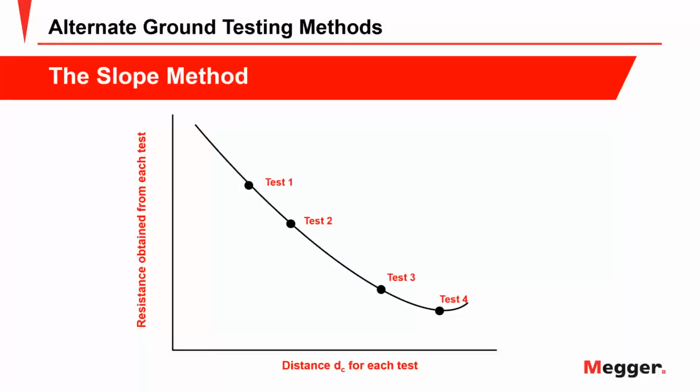And so you can do that once and walk away with it if everything seems coherent. But to be thorough, and especially if you're dealing with third parties, it is a good idea possibly to repeat the test in a few directions and with a few different probe spacings.